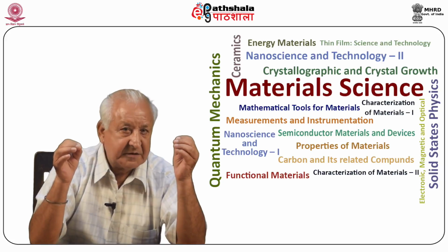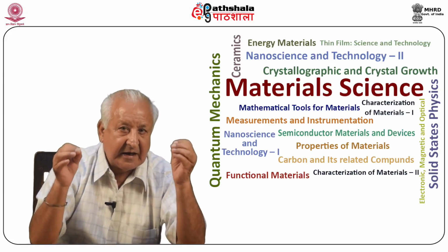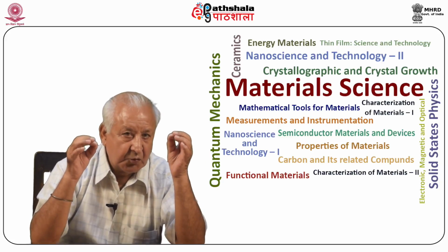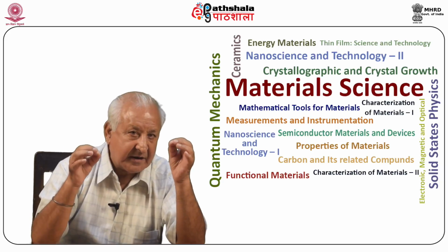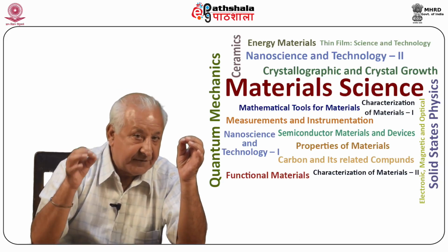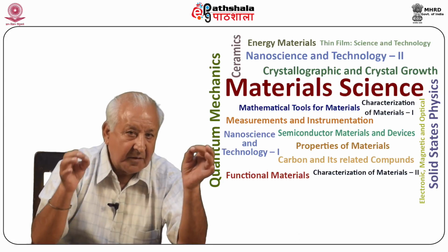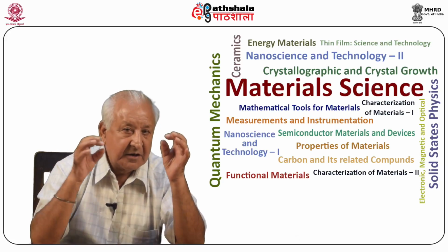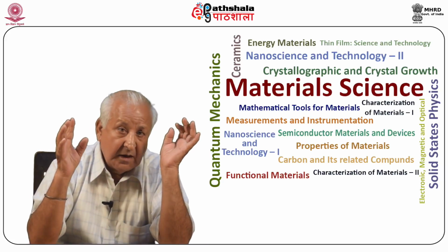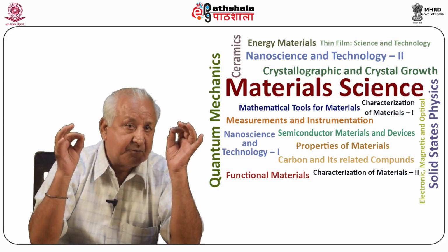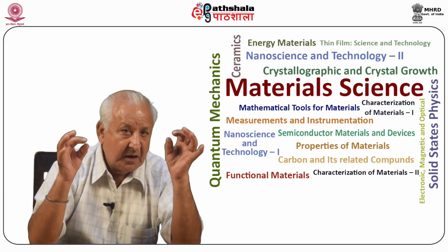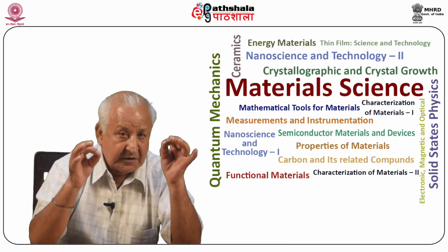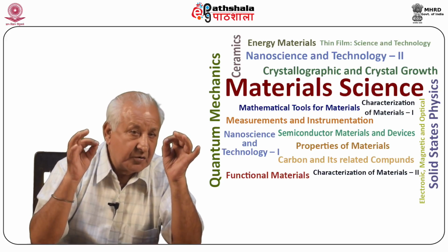One of the main problems is the addition of a second liquid layer above the first. If the encapsulant is too thick, it will act as a thermal blanket, thereby making growth more difficult. If it is too thin, it will not be able to hold the volatile component, which is likely to result in melt stoichiometry problems. In this technique, the crystal has to be pulled through the encapsulant layer. There is every danger of improper draining of the encapsulant from the crystal, thus causing cracking during cool down.